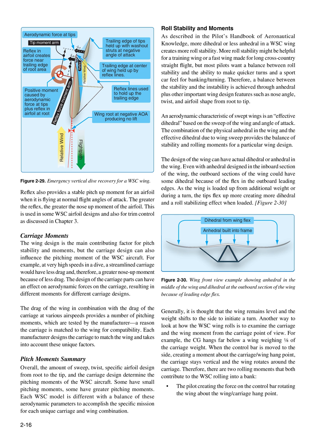An aerodynamic characteristic of swept wings is an effective dihedral based on the sweep of the wing and angle of attack. The combination of the physical anhedral in the wing and the effective dihedral due to wing sweep provides the balance of stability and rolling moments for a particular wing design.